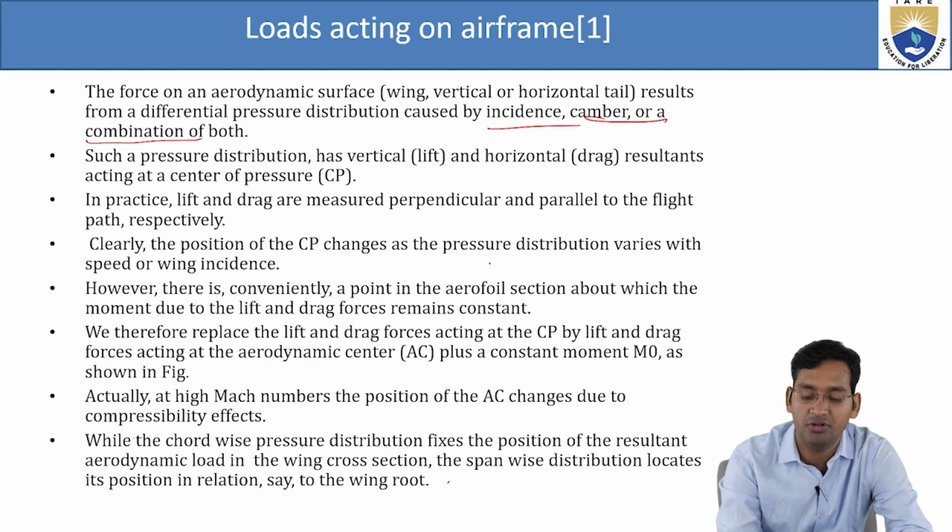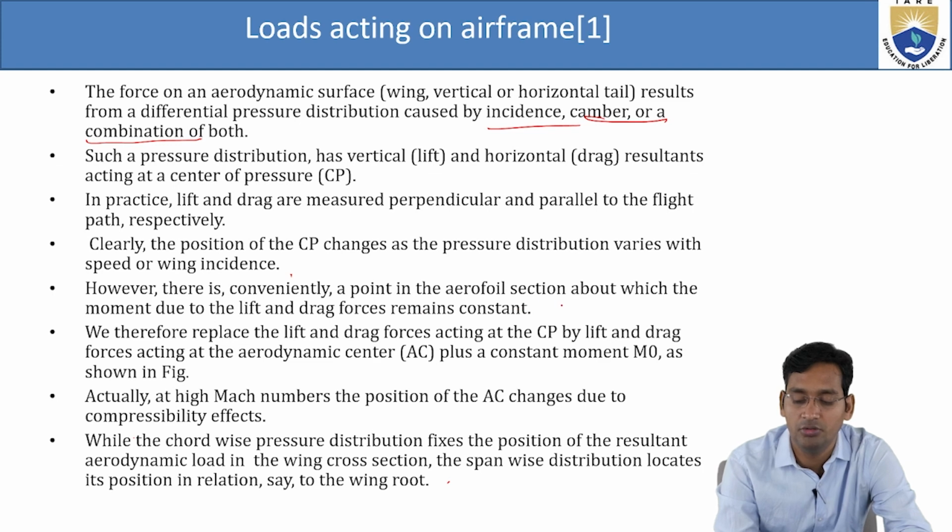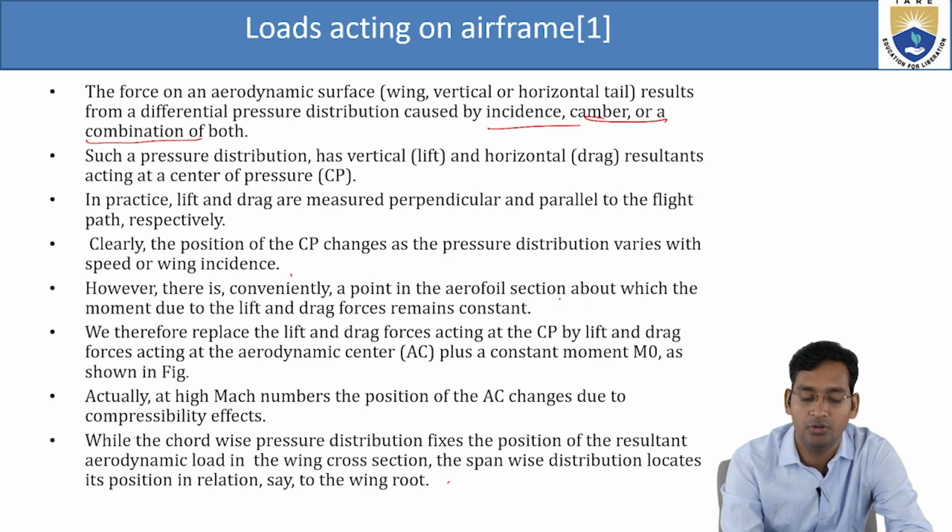Clearly, the position of the CP changes as the pressure distribution varies with the speed of flight or wing incidence. However, there is conveniently a point in the airfoil section about which the moment due to the lift and drag forces remains constant.